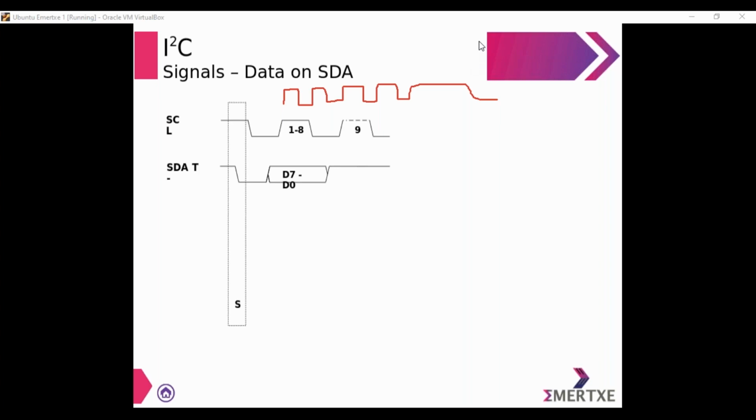Now the first data line that you see is with respect to the master. So the master transmits the second register's address: at every low level of the clock pulse, one bit will be transmitted. At the same time, the slave is going to receive that data at the high level of the clock pulse. So what happens is, at low level, one bit of the data will be transmitted. At high level, one bit of the data will be read by the receiver.